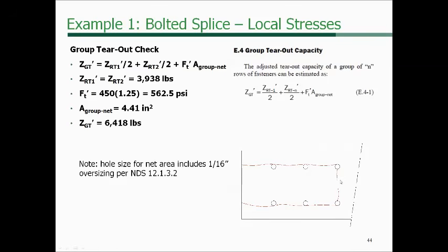We mentioned that this is kind of an art, because we probably have to keep these rows at 5 inches or less, so that's automatically going to sort of max out your tension capacity of a lot of these joint configurations.